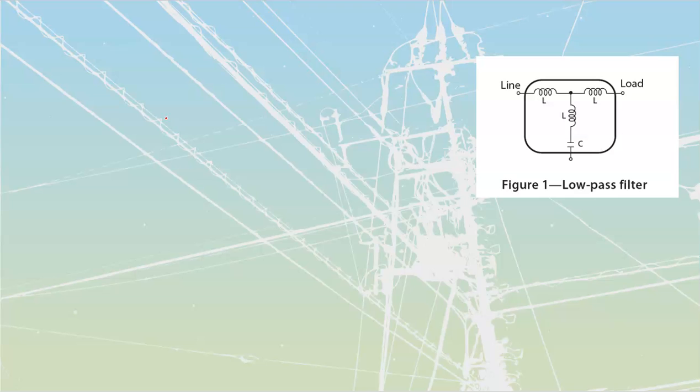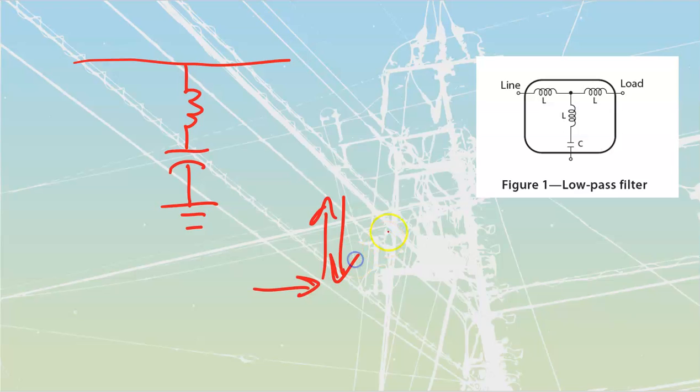All that a filter is, is a circuit that is tuned so that it can dissipate any sort of frequency. If you go back to your second year where we dealt with series RLC circuits, we'll put an RLC circuit into ground here right now. Series RLC circuits have resonant frequencies that they resonate at. And we know that when we hit a resonant frequency, the XL and the XC both counteract each other, which basically leaves us with the lowest possible impedance, the Z, that's left on there, which means that we can pass current through when it's the correct frequency.